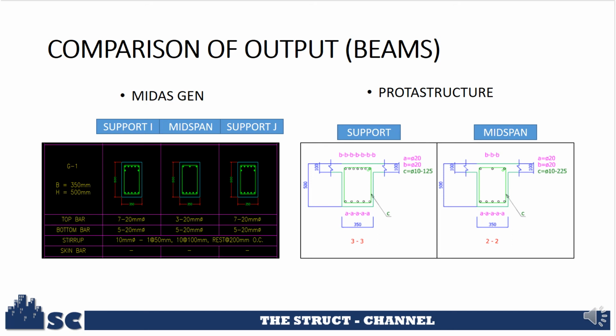In the industry, for the interest of the contractor, to minimize wastage, usually in preparing their bar cutting list they use all the 5 lengths commercially available in the Philippines, which are 6 meters, 7.5, 9, 10.5, and 12 meters. So this is still good as far as the initial estimate of the rebar.